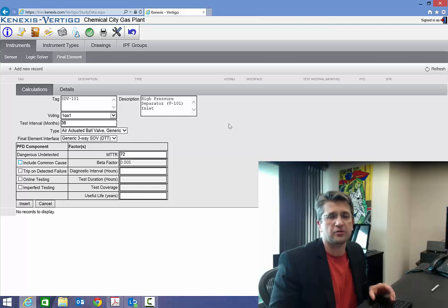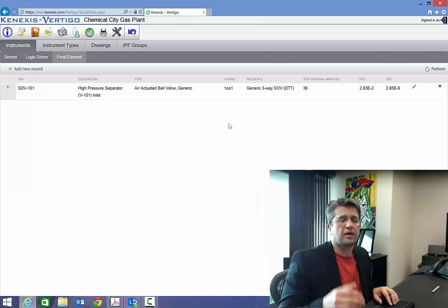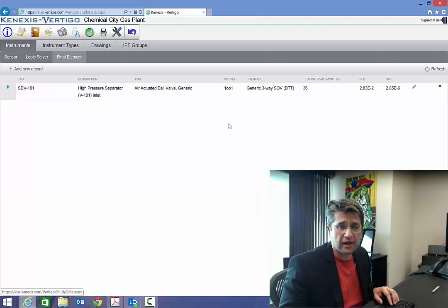and no, we are not going to include common cause, because it is a 1 out of 1 device. And for meantime to repair, we'll just go ahead and leave that 72 hours. We're going to assume perfect testing, and that the testing is all done offline, and click insert. Okay, after I run my calculations, again, you'll see that the PFD calculation and the spurious trip rate calculations have been completed.